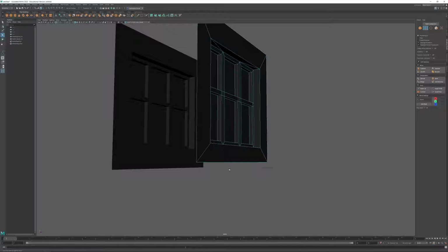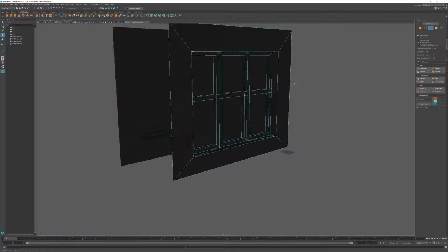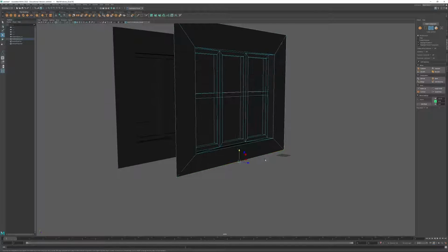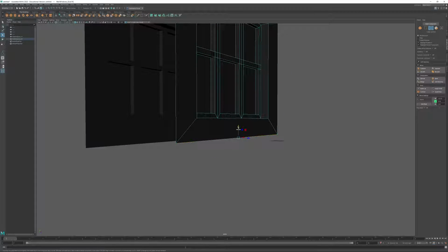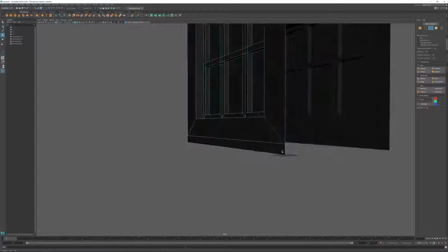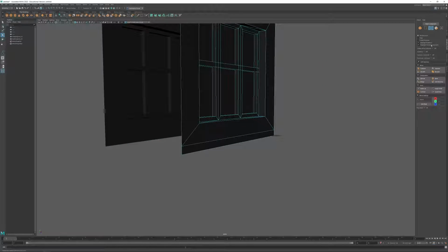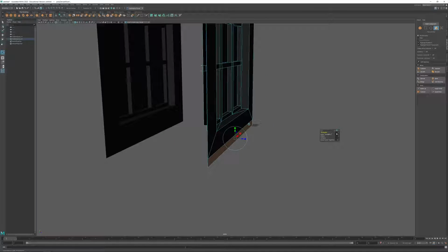This is going to create a gap between this mesh and the bottom of the world. I can select the bottom edge and holding Shift, drag it down. This I will put at 0 in Y, placing it back where it was originally. Then I will grab this face, extrude it, and I think I'll give it a thickness of 12.